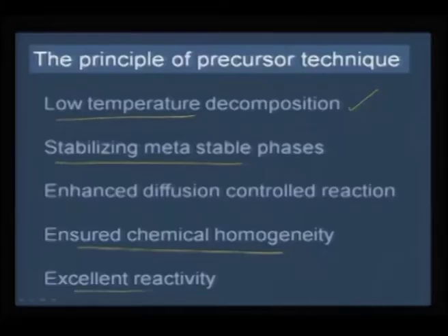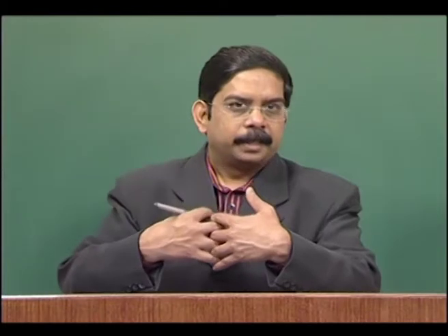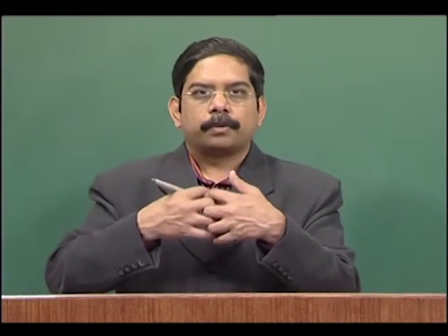And thirdly, there is excellent reactivity, because you are doing a low temperature preparation. Suppose two metal oxides are combining to form a final compound; because they are liberated at low temperature, the general reactivity of these powders will be very high. As a result, any diffusion control processes can be enhanced because of this low temperature approach.